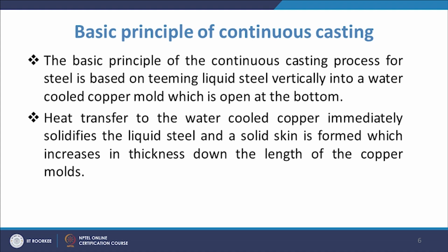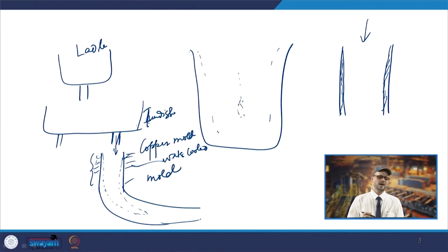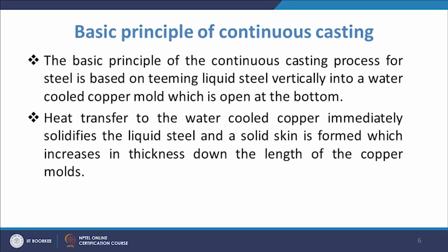So, we discussed that the liquid from here will come down, and since this is a copper mold which is externally cooled by water, it immediately starts solidifying from this point, because the thermal superheat will be arrested, and once you go below the liquidus temperature, the solidification will start. First of all, a very small fine skin will be formed initially, and the thickness of that shell will go on increasing further.